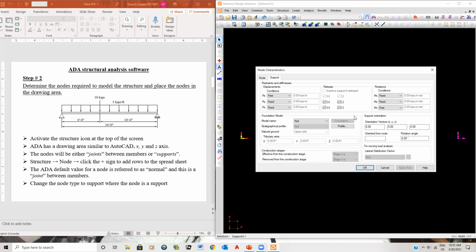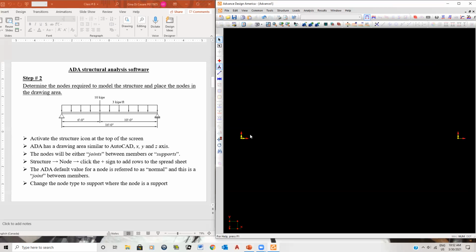instead of the MZ. Yeah, okay, I freed the MY, but I don't understand why. You understand? If we're doing the three-dimensional, yeah, exactly. And I'm glad you made that mistake because that's a classic mistake, okay? Like I said, I apologize, it's a three-dimensional program, but that's what it is. But you see, what's happening is that this is your Z axis, and the rotation of the beam is happening with respect to the Z axis. Do you follow? And therefore you have to free MZ.